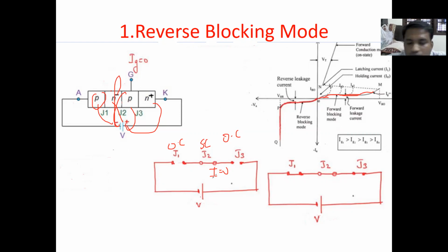So if you increase the voltage, sorry, this is the reverse one. Reverse one means this is the third case, because I have applied negative to P type. So negative means reverse, this is the third quadrant characteristics. Okay, reverse, this is the blocking mode region, reverse blocking mode.